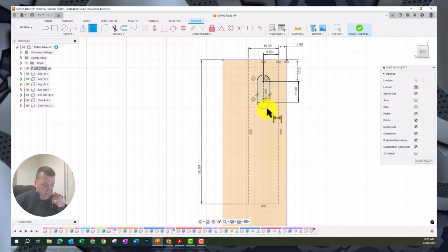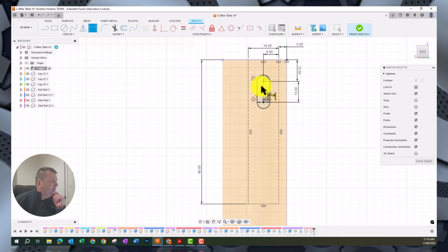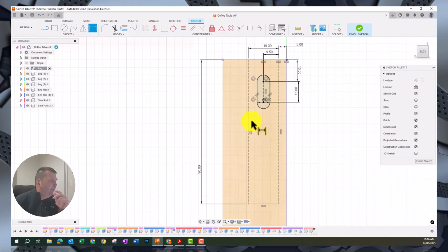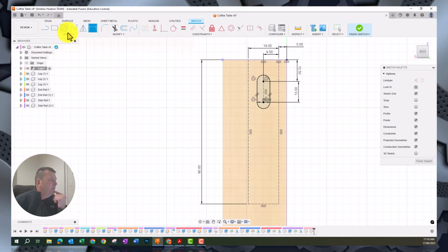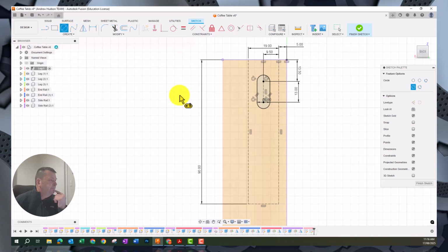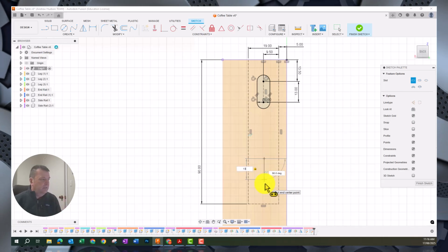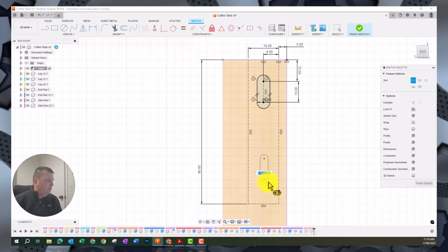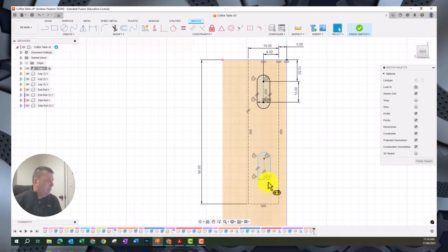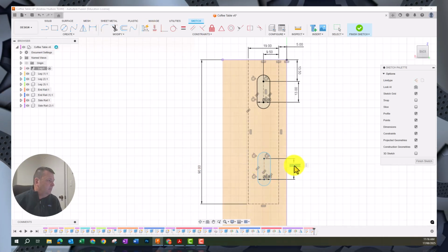Like that. I think that's all we need. So that's centering that to where our hypothetical end space is going to go. We're going to create a second one of those to do another slot down the bottom here. So it's 13. Press enter a couple of times, then go 8, press enter. Get your dimension tool, dimension this middle bit to 13.